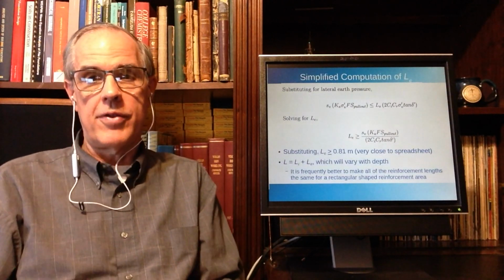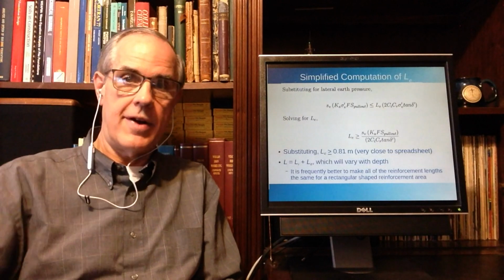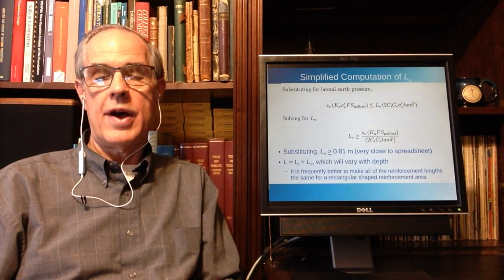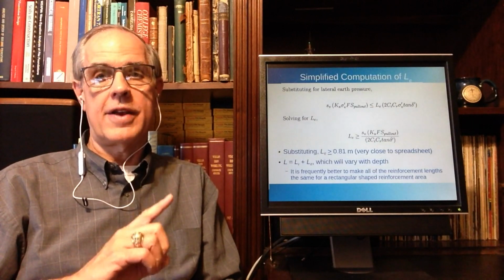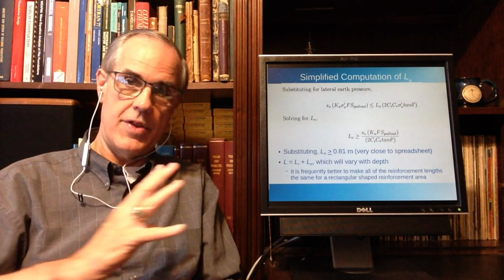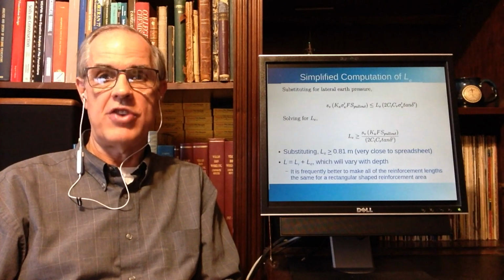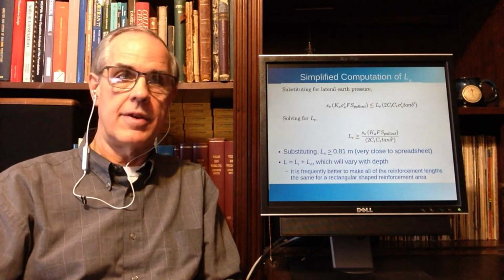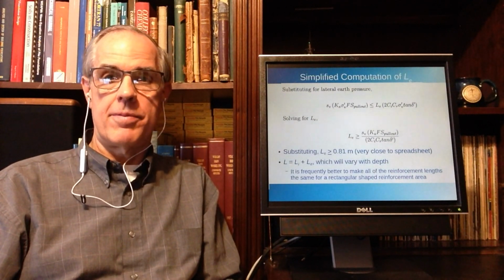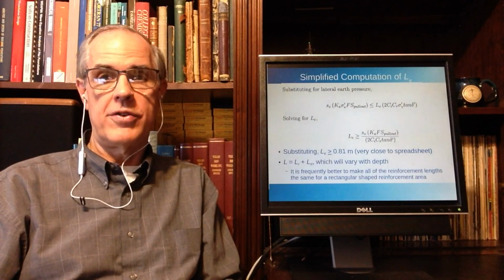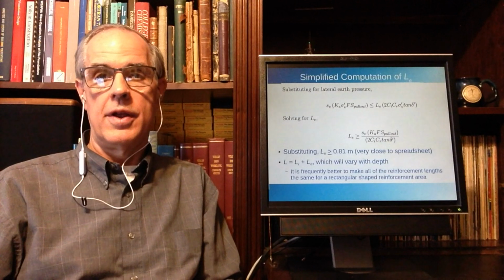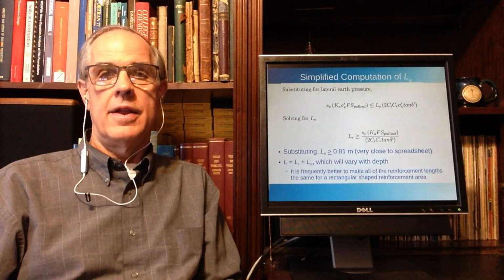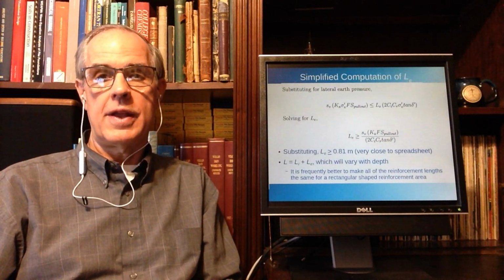In other words, once you solve those two problems, then you have to make it longer to fix it. In this case it will not affect the strength of the geogrid, because the driving force doesn't change by making the reinforced backfill deeper. There are certain situations, depending on whether it affects the retained backfill in a certain way, where it could, but strictly speaking, it will not.